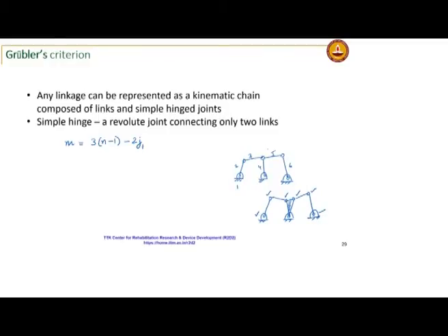I am saying I do not have any 2 degree of freedom joints in the mechanism. Now, let n be my total number of links. It is a closed chain, so I do not have any singular links. Let n2 be the number of binary links,